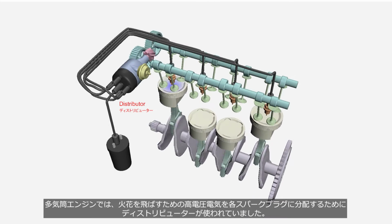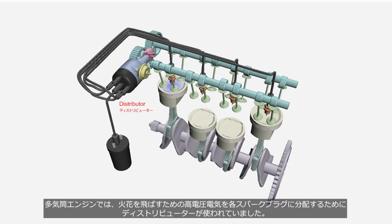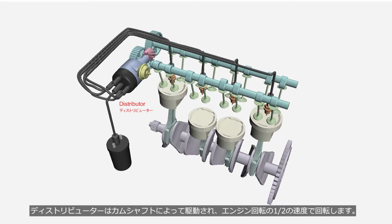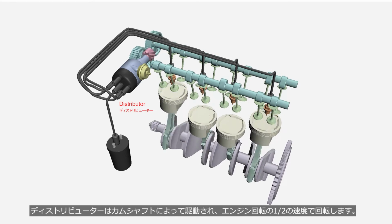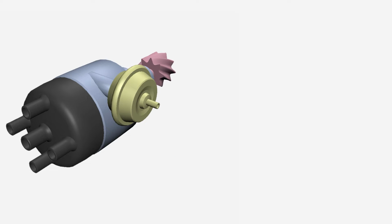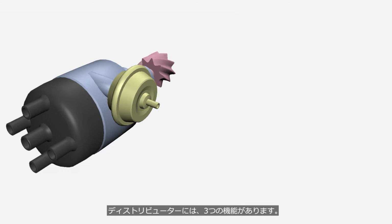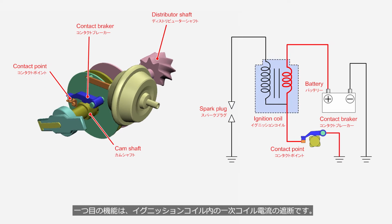In multi-cylinder engines, a distributor is used to distribute high-voltage electricity to each spark plug in order to create sparks. The distributor is driven by the camshaft and rotates at half the speed of the engine rotation. A distributor has three functions. The first function is shutting the primary coil electric current in the ignition coil.